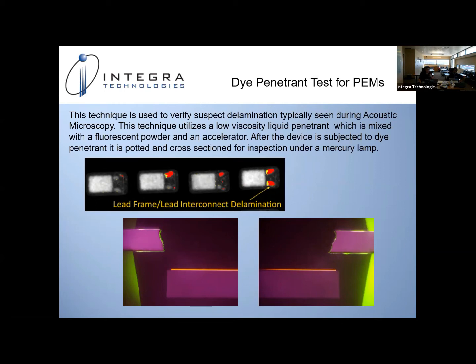If it's a ceramic capacitor, a stacked capacitor, CSAM is performed on those here and there in the industry, but you're not going to get the full depth of the capacitor stack. You're only going to reach a certain depth to look for voids.